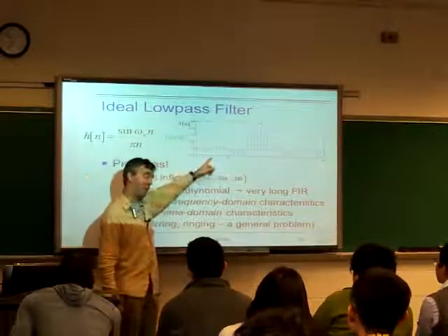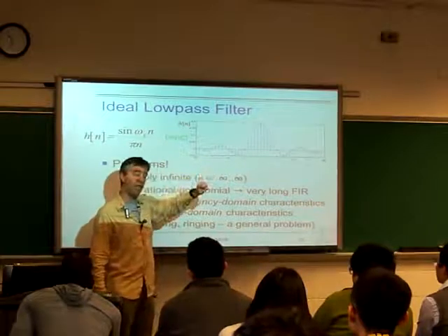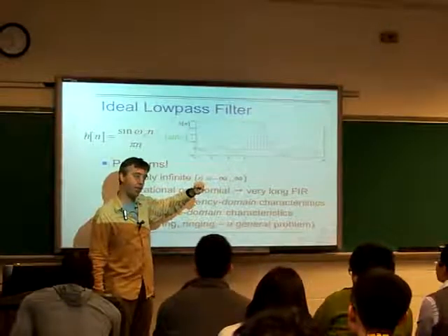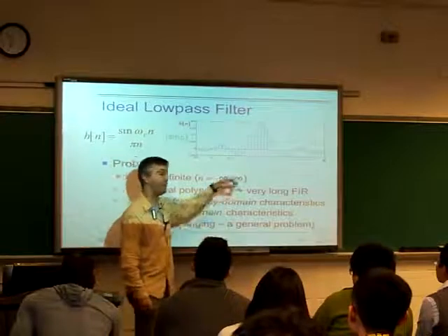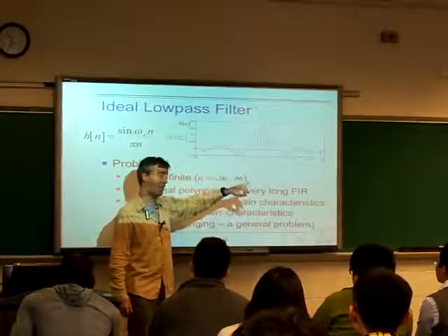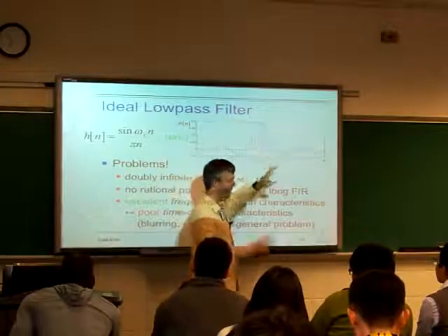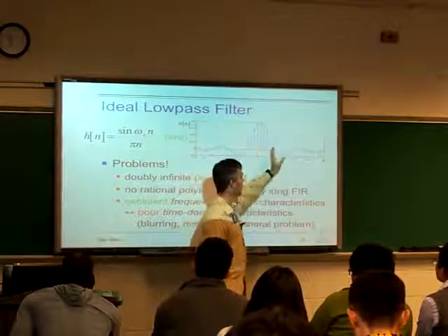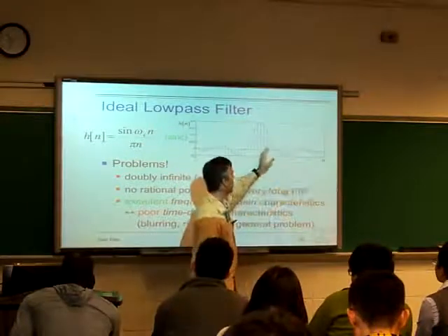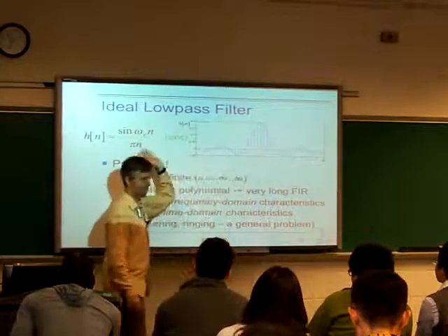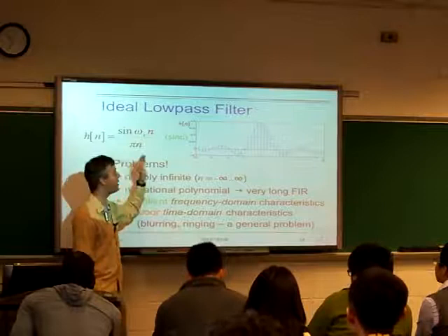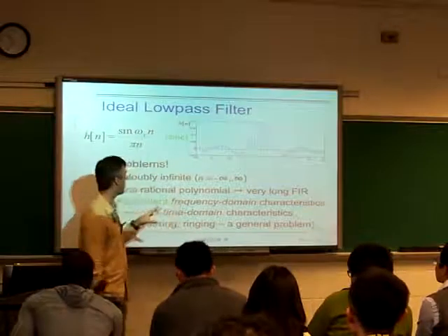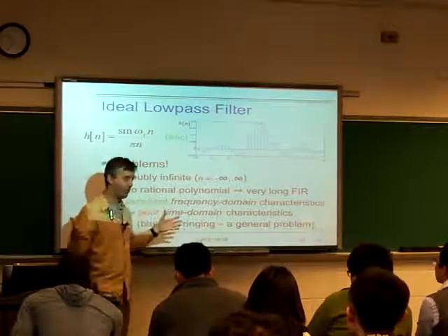This is an infinite impulse response. Okay, fine, we've seen infinite duration impulse responses before. Anything with a pole has an infinite impulse response. But this is infinite in both directions. In theory, if you had this filter, you put an impulse in and it carries on forever, but it would also have had to start infinitely before the impulse arrived, to get this full impulse response. So it's non-causal, and it's infinitely non-causal.